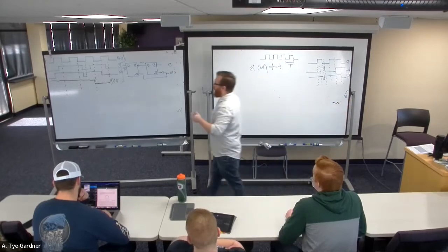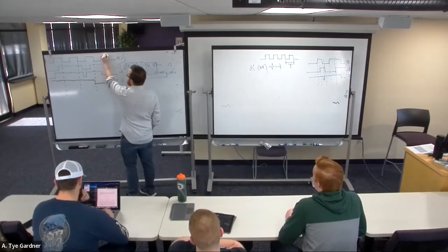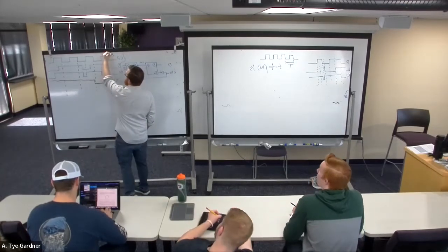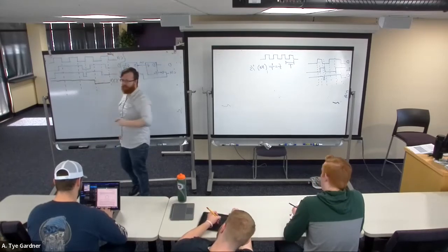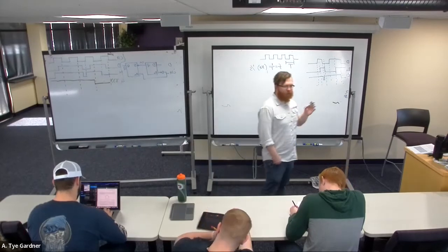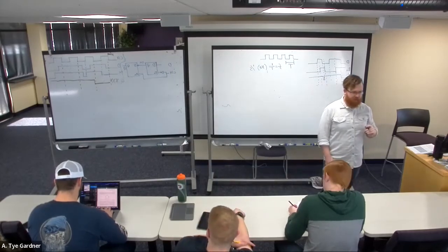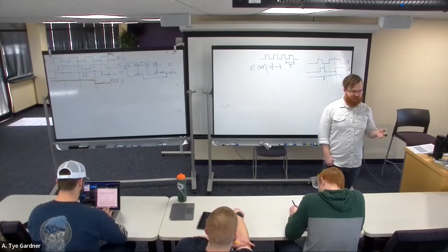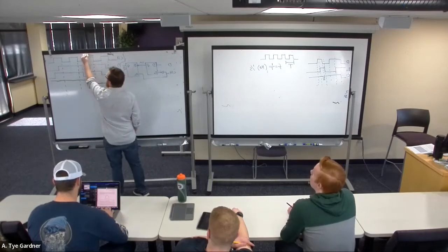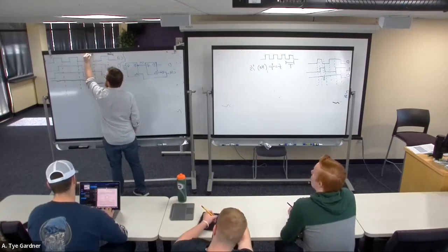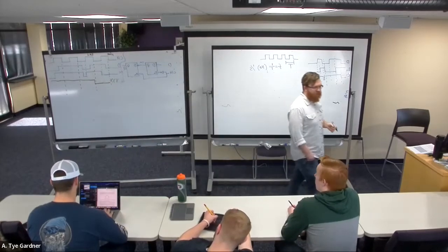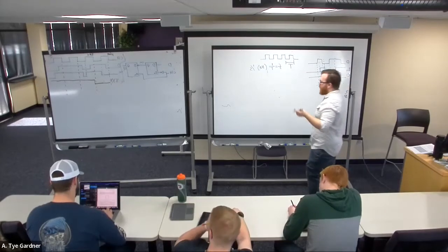And we call the time before the clock that I have set up the signal the setup time, T sub SU. Setup time is the amount of time that a specific device is required to have its input stable before the clock changes. Similarly, the time afterwards is T sub H, hold time, because I have to hold it afterwards. And the reason is pretty simple.